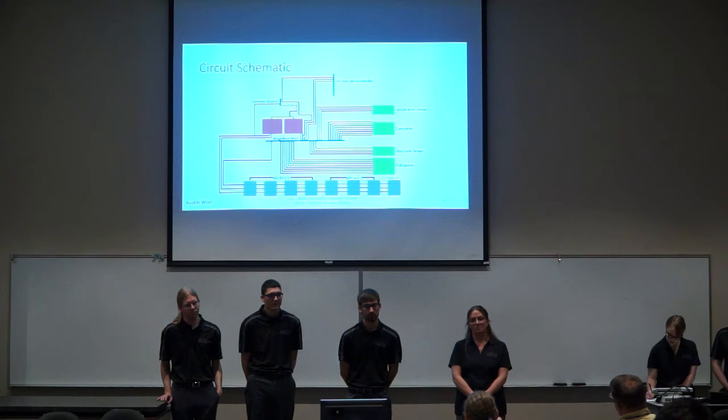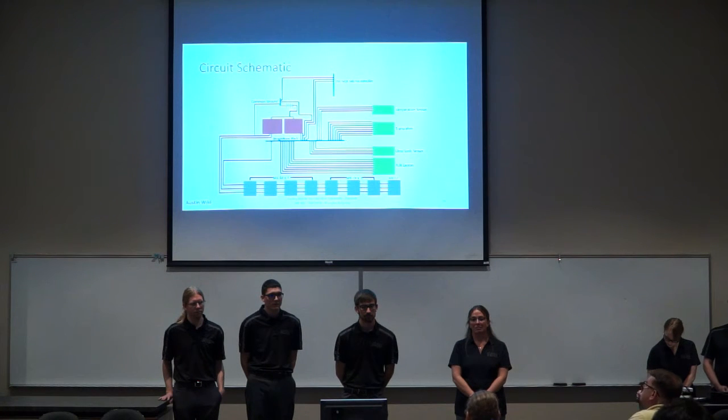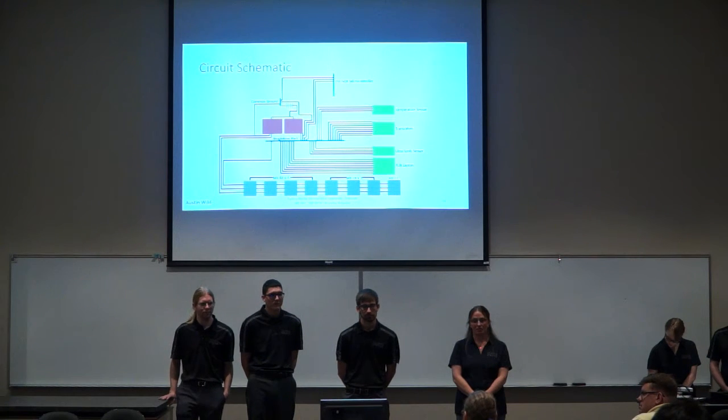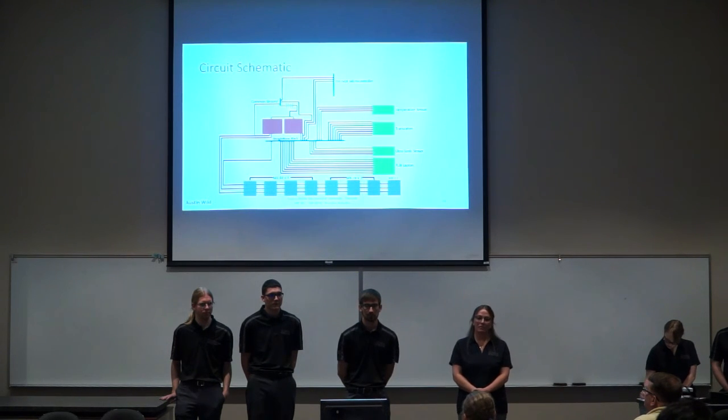Because we'd like to be able to tell you if something is going to work. I can tell you right now, if you don't have any additional components, that temperature sensor is not going to work, nor will the regulator for the 5-volt supply. You'll require numerous additional components there. Why we want to see that is so that we can advise you if it's going to work or not, the way you presented it.